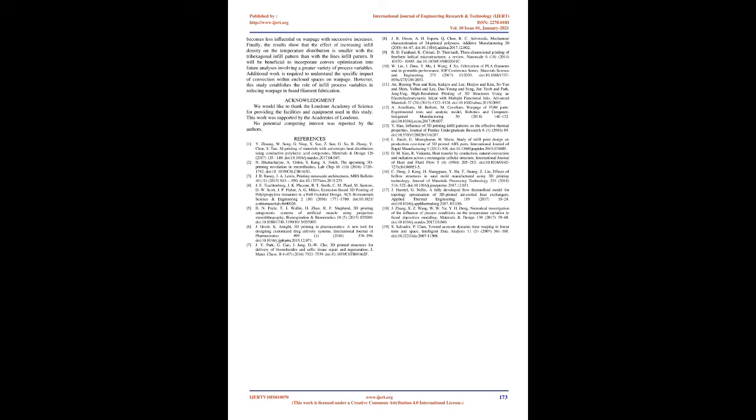Rows 5 and 7 show the results of the DTW algorithm on the heat flow trajectories of the disks with 10% and 20% infill densities with the lines infill pattern and the trihexagonal infill pattern. Rows 6 and 8 show these results for the disks with 20% and 30% infill densities with the lines infill pattern and the trihexagonal infill pattern. For both patterns, the similarity score for the comparison between 10% and 20% infill density is larger than the similarity score for the comparison between the 20% and 30% infill density.